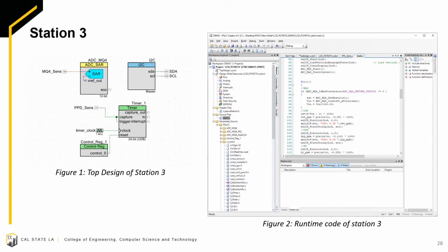Figure 2 shows a small sample of the code. The MQ4 sensor in particular is capable of detecting several different types of gases on its own. The PSoC will get these values, derive the sensor's readings into each gas's appropriate concentration, and perform the necessary tasks before taking another reading. Those tasks being displaying on the LCD screen, relaying the information via the LoRa module, and storing these values within the FRAM storage.